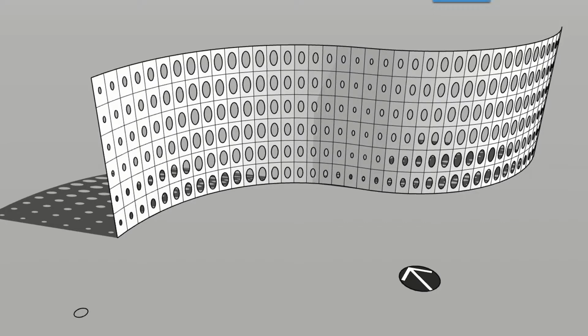So this one is just a simple example, nothing too fancy. But it is something that would be hard to model by hand. You've got a curved facade in this case, and you basically want to vary the aperture size by the direction to south. And that's a really easy script that you can implement in no time, and you can model off that. You can use that as a basis for modeling.